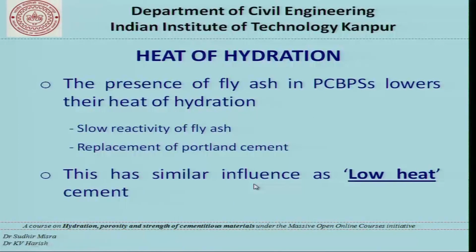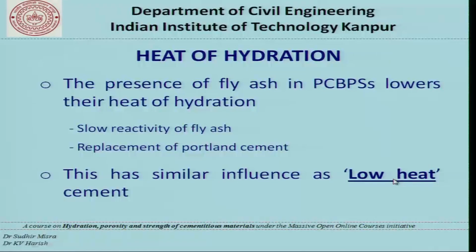And in Portland cement we also have several special categories, such as low heat cement, high sulfate resistant cement, or in other words super sulfate cement, and several other types of blended cements. So remember that in low heat cement or super sulfated cement, we don't have any additional ingredients. We have only the same ingredients as in the production of Portland cement, like C3S, C2S, C3A and C4AF. The only difference between these special cements and Portland cement is that the composition of the compounds is slightly changed in order to suit the requirement.